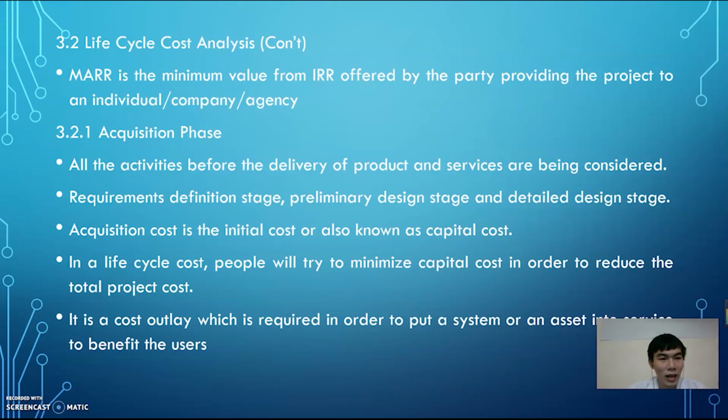It can be further classified into three stages, which are requirements definition stage, preliminary design stage, and detailed design stage. Requirement definition is to identify the client's requirement and the required documentations, the preliminary design stage is to identify the feasibility study, and detailed design is for the detailed design of the building and the site.